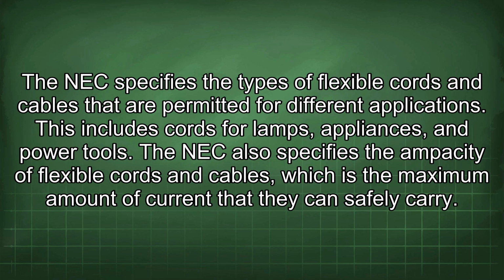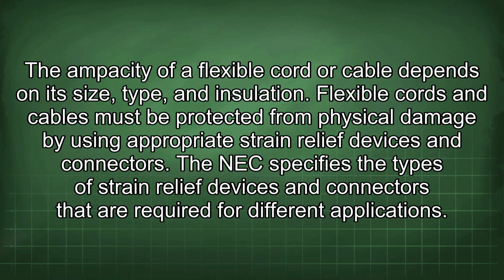The NEC also specifies the ampacity of flexible cords and cables, which is the maximum amount of current that they can safely carry. The ampacity of a flexible cord or cable depends on its size, type, and insulation. Flexible cords and cables must be protected from physical damage by using appropriate strain relief devices and connectors. The NEC specifies the types of strain relief devices and connectors that are required for different applications.